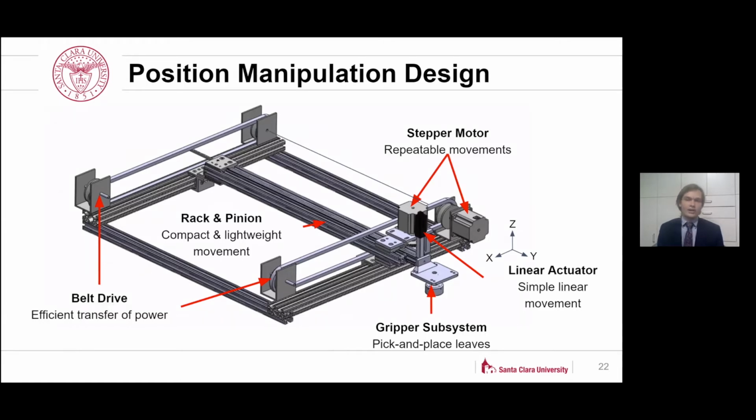The Z stage is a linear servo, and this is mounted to the end of the Y stage. It moves between an on and off position controlled through pulse width modulation, both to touch the conveyor or the Basil leaves, or to retract and go to the can. And all movement is limited and calibrated with limit switches on each corner. This design is similar to a gantry style robot. One of the big differences is the actual movement of the robot is directed outside of the frame, and all this allows the gripper to move.